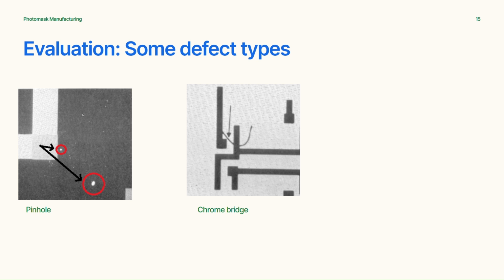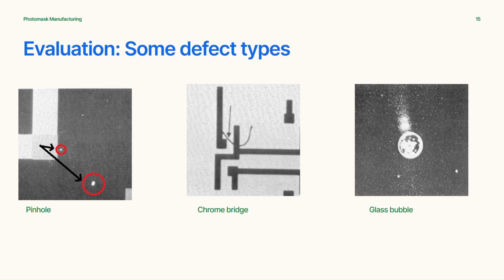Now, this last defect is not something you can fix, and generally is a killer, the glass bubble, and it appears in the quartz. Generally, you would evaluate your quartz, and if you find any glass bubbles, you can't use that quartz. You just have to toss it out.